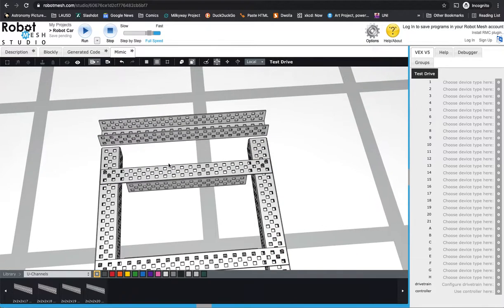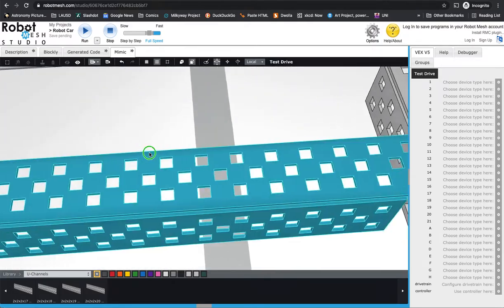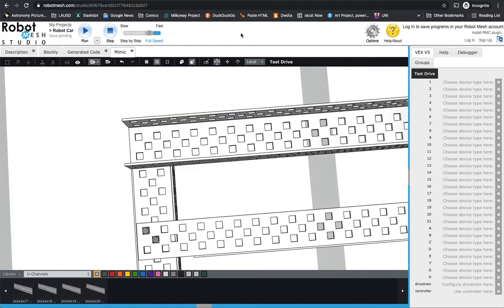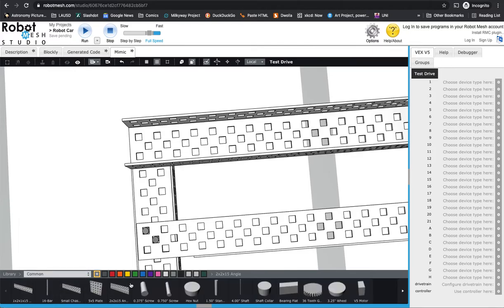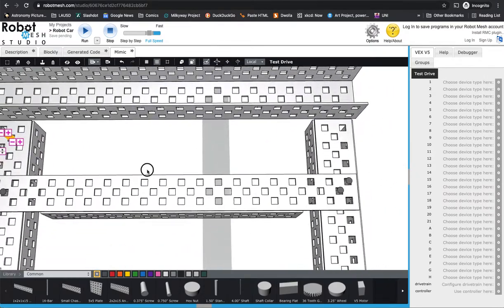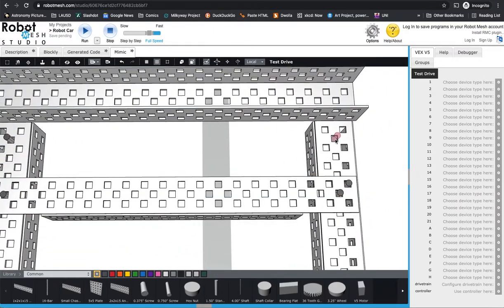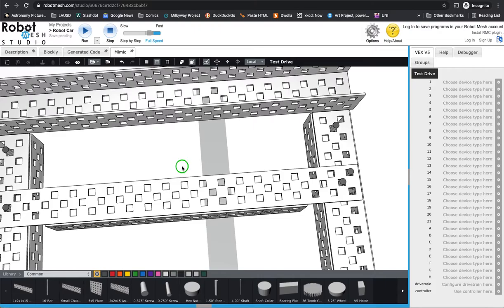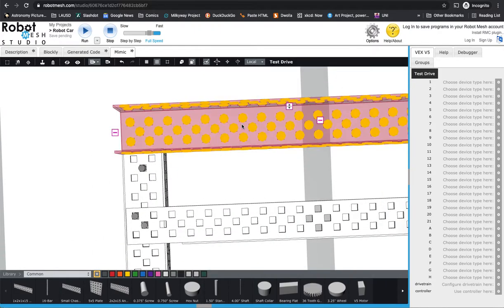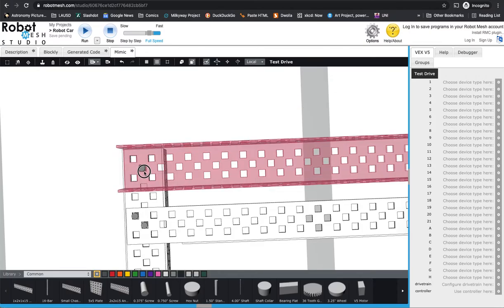And it's going to attach to the very back holes. This hole here and this hole here. So let me put a screw in there using the auto tool again. Yeah, keep switching back and forth to those tools. Screw in the very back hole right there, and screw in the very back hole right there. And then again, use the auto tool. I can click on this, the very end hole here, click and drag, and snap it in place.